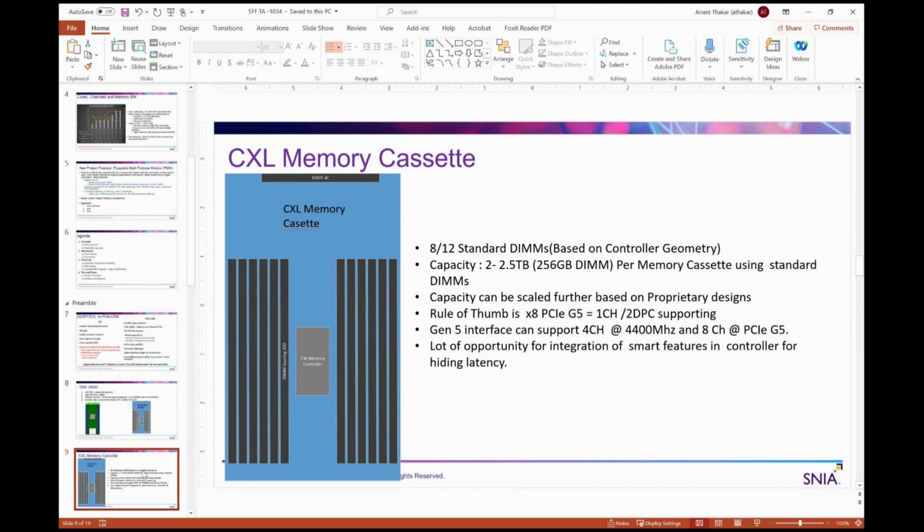Okay. So this is not the packaged memory, but rather pluggable DIMM modules. Correct. What is the connector at the back? It's an EDSFF connector. The connector at the back is a x32 EDSFF 4C plus 4C connector. This is the new connector which we are defining. Oh, so we will leverage it from the E3 side. Yeah, E3, which was probably leveraged from the Gen-Z connector.